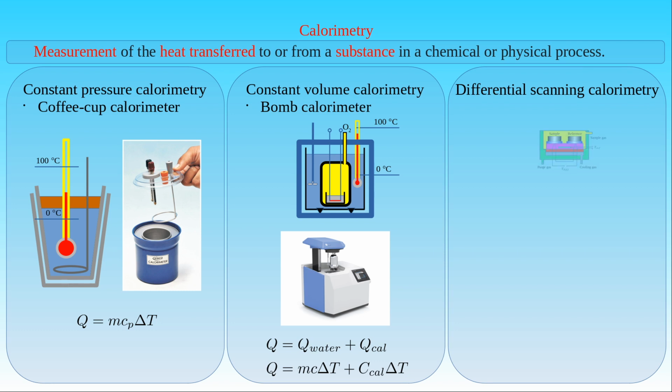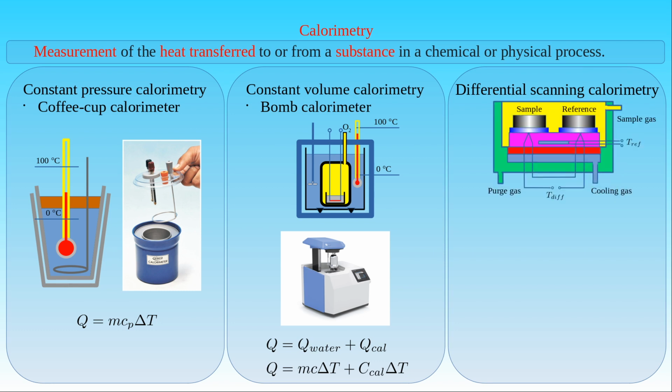The figure shows a differential scanning calorimeter, which consists of the sample and reference holder, also called sample unit, the heater with a heat resistor, and the heat sink working with cooling gas, which has enough heat capacity compared to the sample. The lid of the sample holder has a hole to allow the escape of some amount of the sample and its exchange with the surrounding gas if it is vaporized.